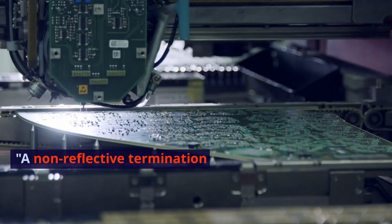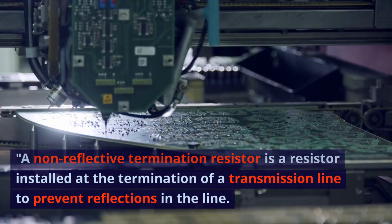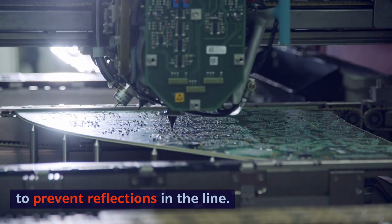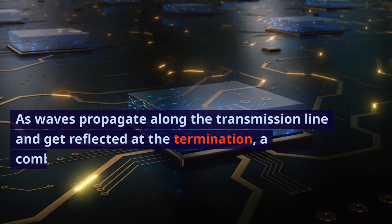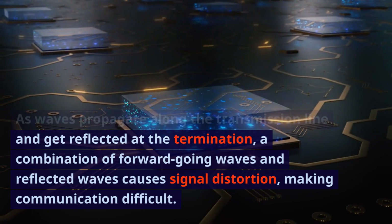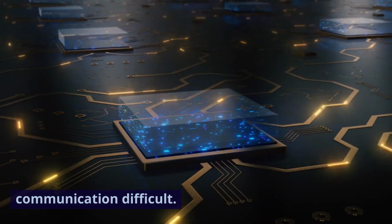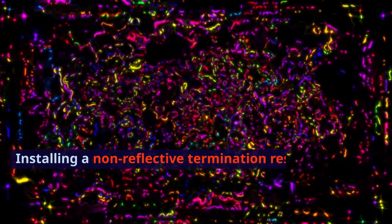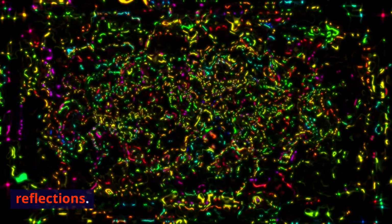A non-reflective termination resistor is a resistor installed at the termination of a transmission line to prevent reflections in the line. As waves propagate along the transmission line and get reflected at the termination, a combination of forward-going waves and reflected waves causes signal distortion, making communication difficult. Installing a non-reflective termination resistor either completely or partially prevents these reflections.